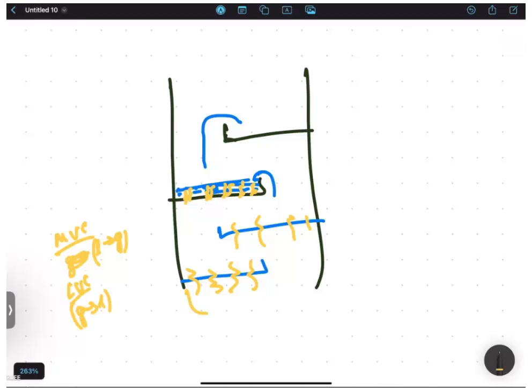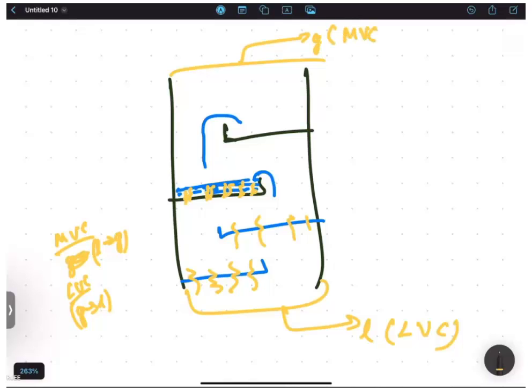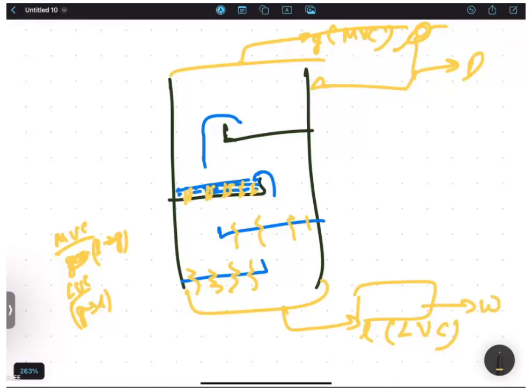So from the bottom, the liquid that we get is rich in the low volatile component, and from the top, the gas that we get is rich in the more volatile component. Then we will send it to a condenser, and we will get our distillate. If we want, we can put reflux. This we can directly put into the reboiler. From the reboiler, we will get our residue, and we can put some boil up vapor inside. So these are the things we will do in distillation.